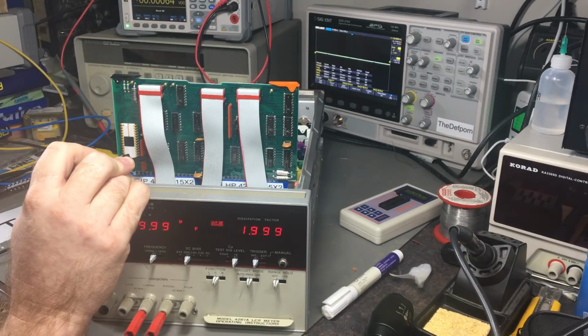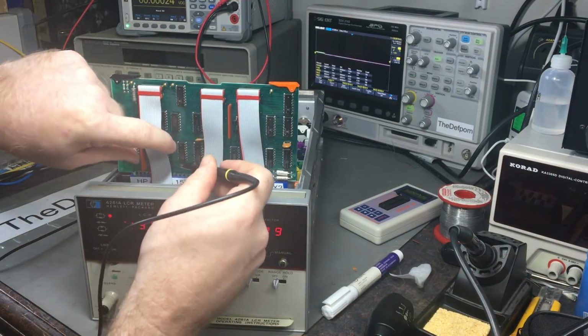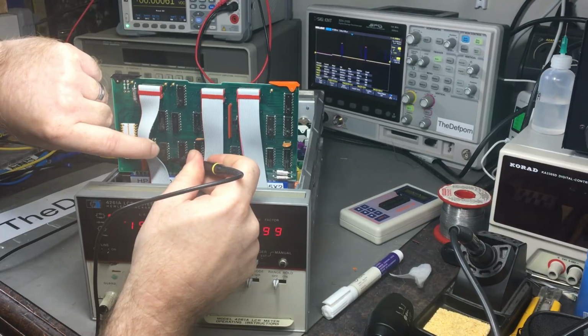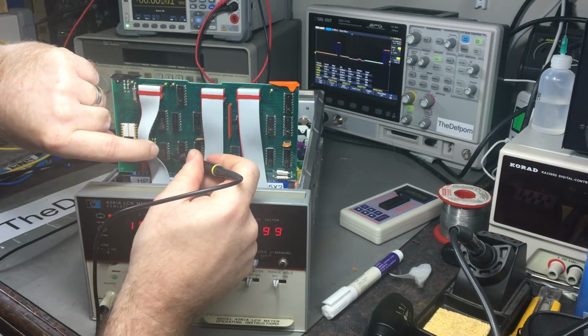That's correct, sorry. I just got a chart, this is what it should be. So yeah, that should be low, that's fine. So pin 8 over here. That should be pulsing again, yeah. It's got a couple of pulses there, which is interesting. That's high low. And pin 10 should be pulsing as well, by the looks of it. And it is. So those look right.